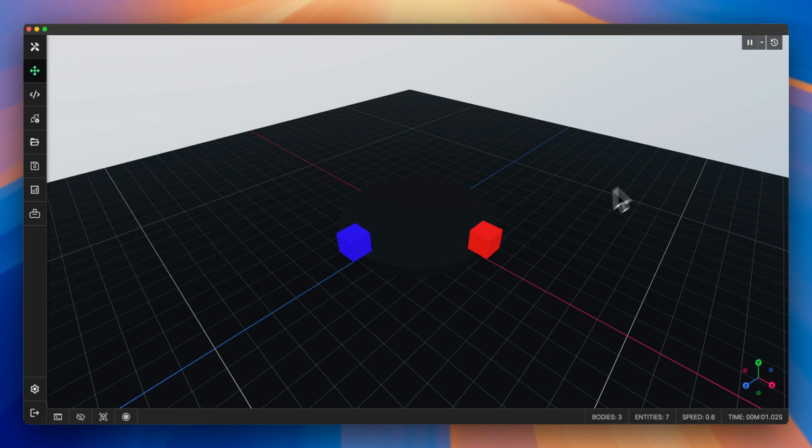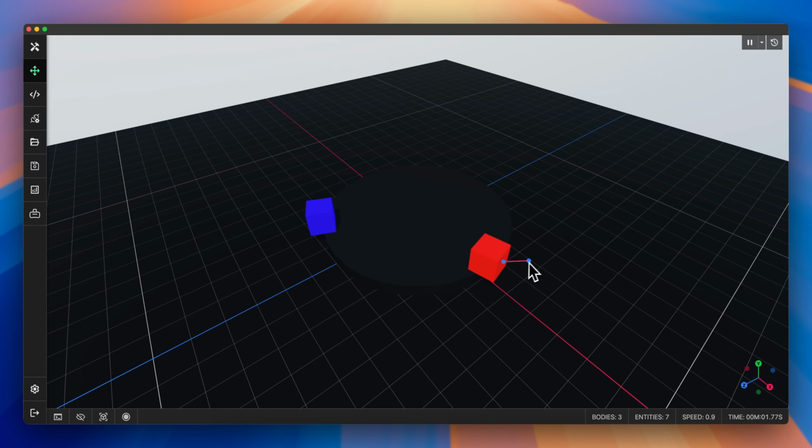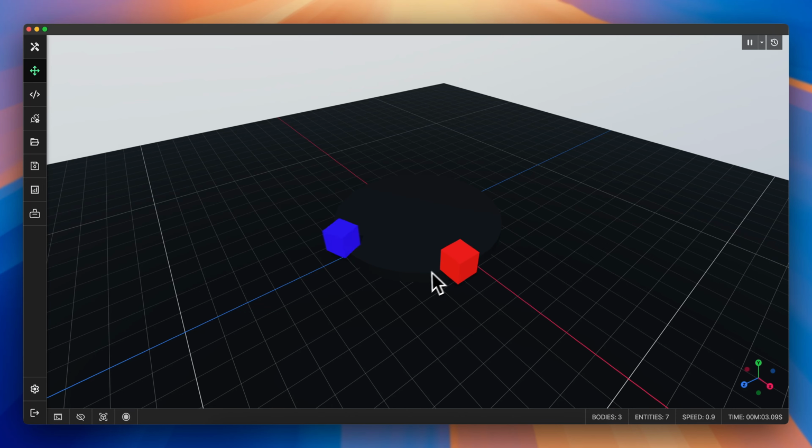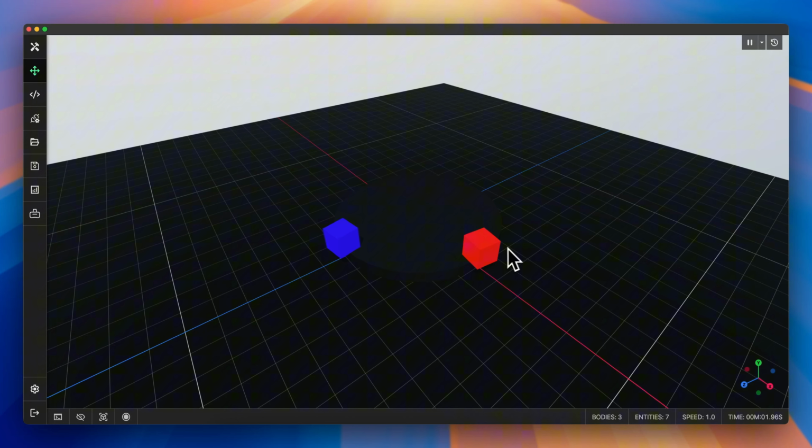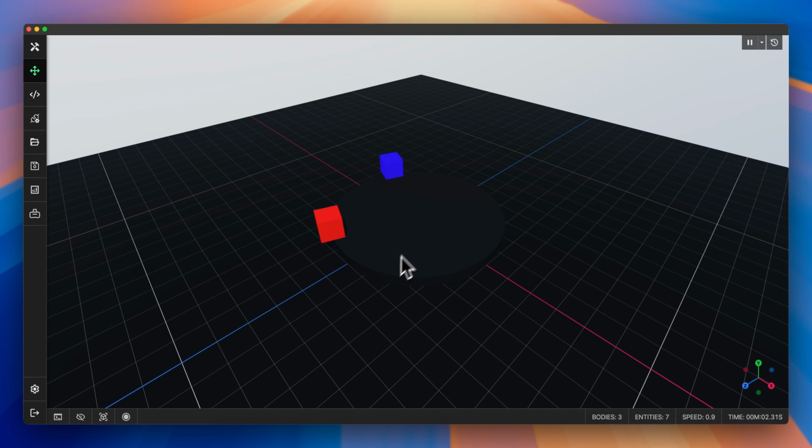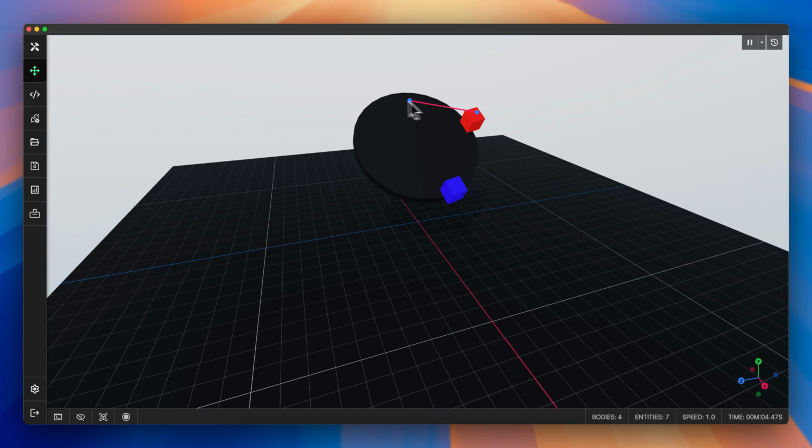We've added a brand new transmission component. This component can be used to relate two joints. The position of one joint can be related to the other through a given ratio. You can relate a prismatic joint to a path joint, a revolute joint to a path joint, a prismatic joint to a revolute joint, a prismatic to a prismatic, a revolute to a revolute, and finally a path joint to another path joint. This component is very powerful since it allows you to create complex relationships between joints in your ProtoTwin models.